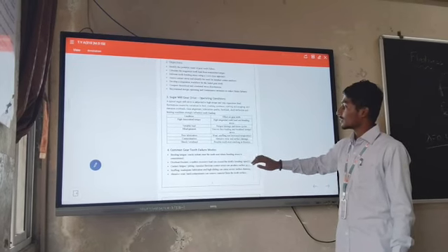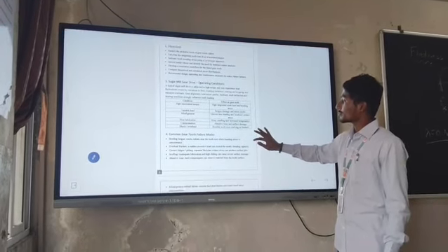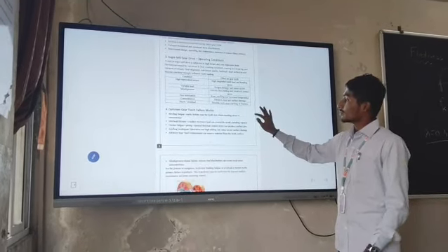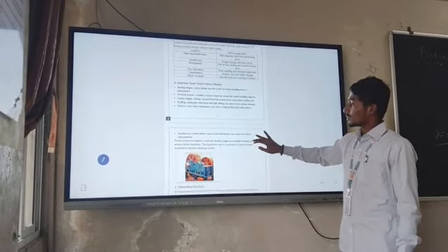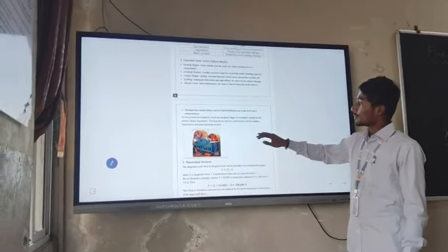Next one is common gear failure modes. First one is bending fatigue. Next are overload fracture, contact fatigue or pitting, scuffing, abrasive wear, and misalignment related failures. From the present investigation, tooth root bending fatigue or overload is treated as the primary failure hypothesis.